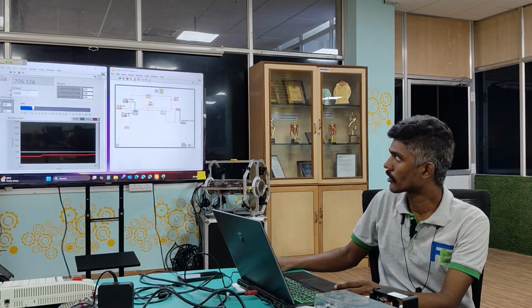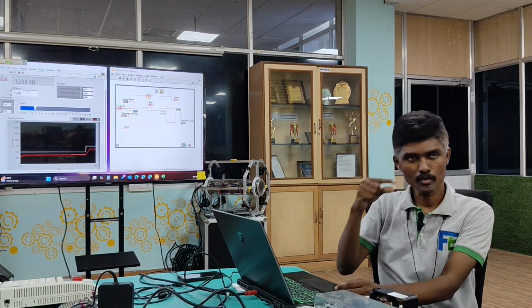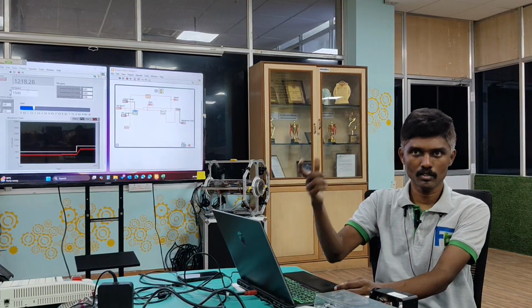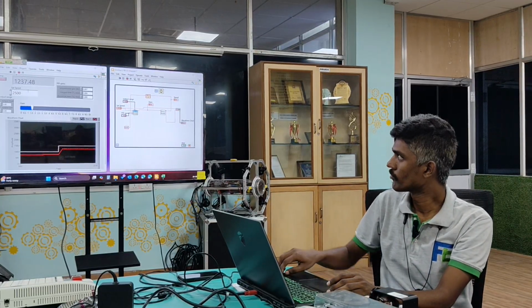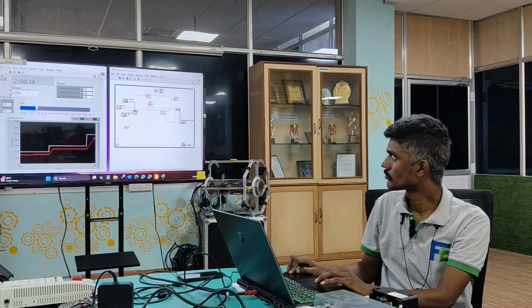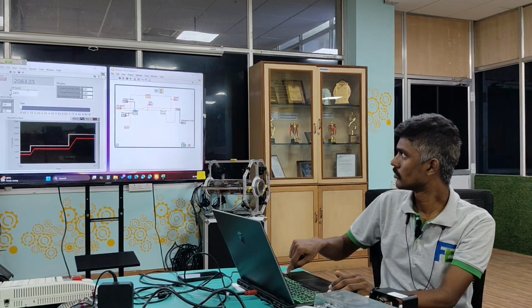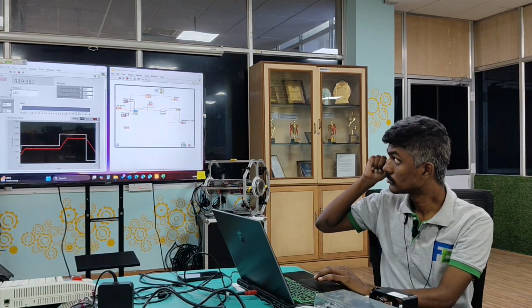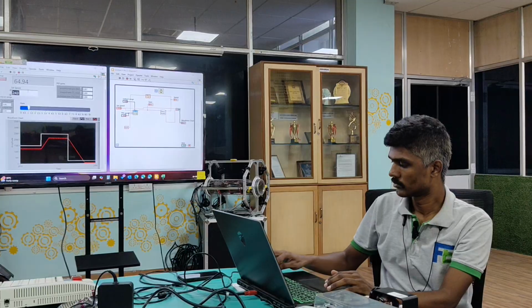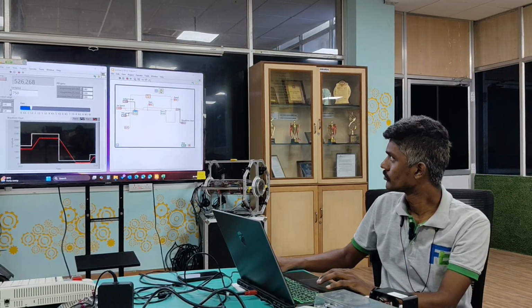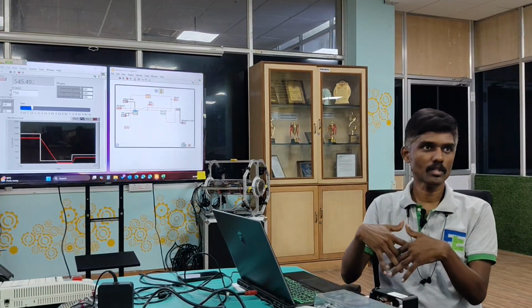I want to check this constant error. So increase the speed to 1500. Your system should respond. It should increase your actual value, and so the output also needs to increase, but there should be a small band. And once you get the 60 to 80% of your band value error, then you start touching the next parameter.